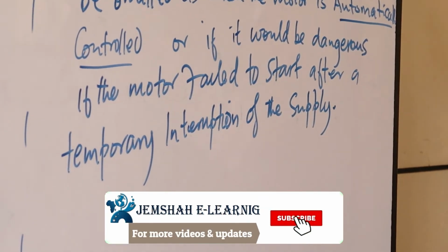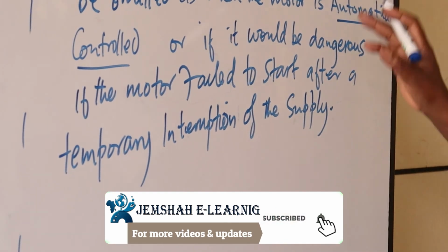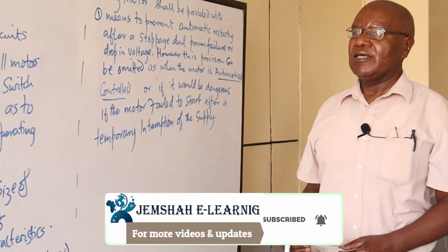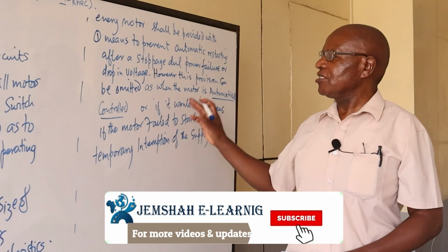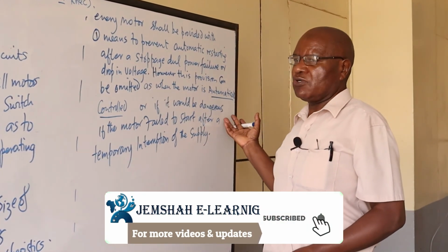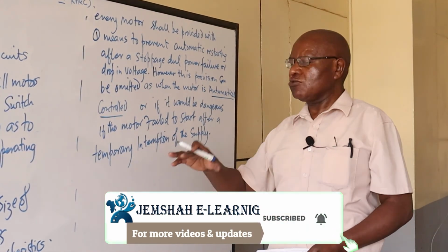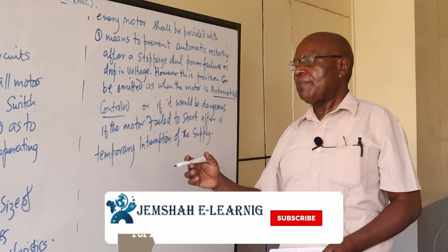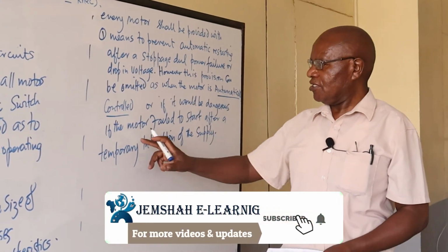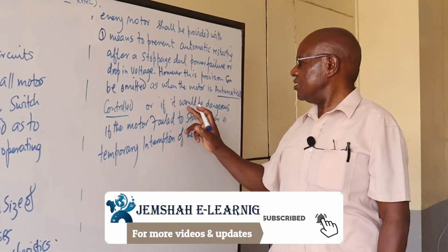So that is a key recommendation of IE, means to prevent automatic restarting, and these are the two exemptions. If automatically controlled, or if it would be dangerous for the motor not to restart when the power comes back. Of course, this second bit, failure to start, dangerous.